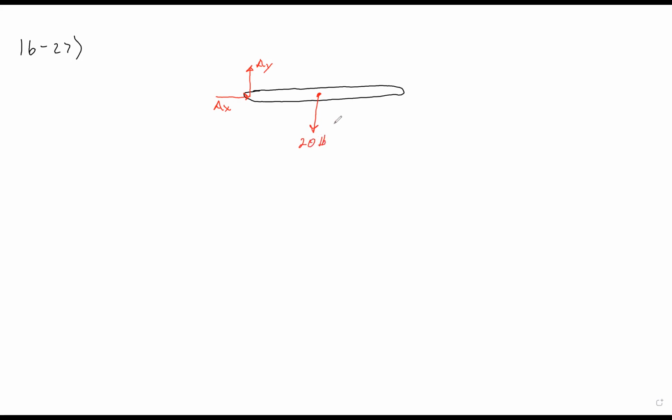Now, they say slender rod or slender bar specifically in the problem. That is a category for a particular shape, right? I will show you how important that word is in a minute. First of all, let's begin the analysis, because I'm going to tell you right away that this is a two-dimensional problem, just like in statics, and therefore you can do 3 equations per free body diagram for two-dimensional objects. For three-dimensional objects, you can do 6 equations per free body diagram.